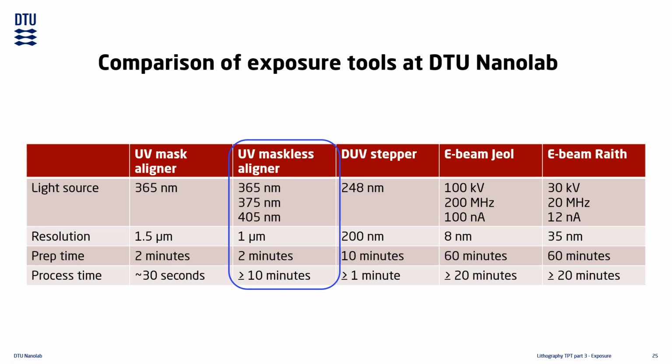Each tool has one specific wavelength, so it is important to select the correct tool for the resist you are working with. The processing time is a bit longer than the mask aligner, but it is far easier for alignment and reliably produces slightly better resolution.